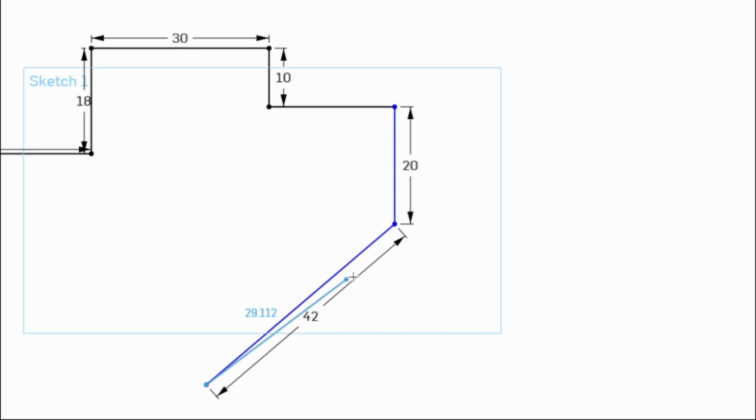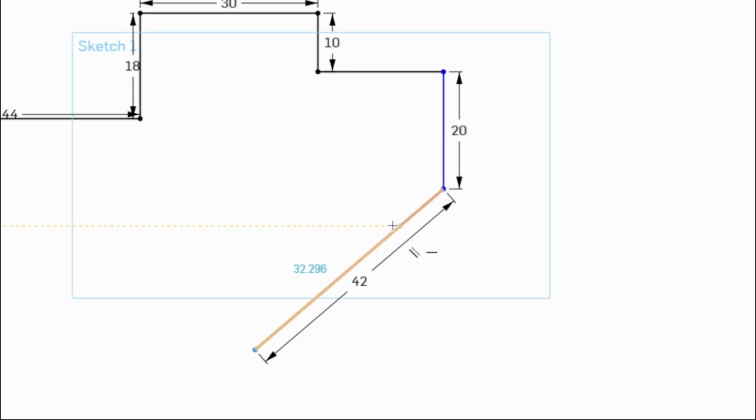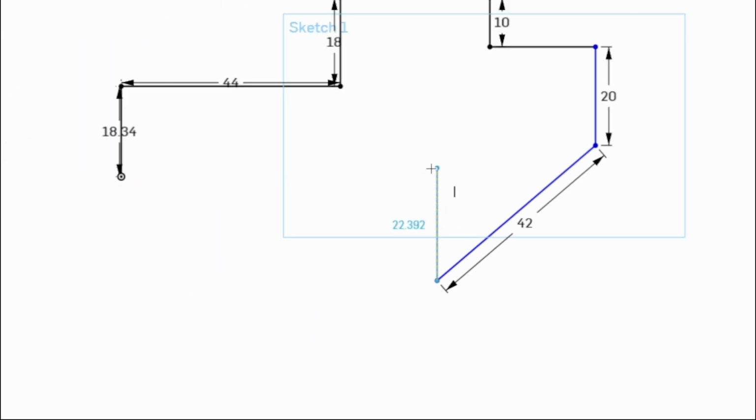It's important that when you're doing angle measurements too, if I were to draw that as a straight line or a horizontal line, I'm going to have to delete some sort of constraint. So it doesn't have to be the exact angle you want. We're going to add that later with the dimension tool, but make sure it's at least at some sort of angle that's not straight up and down or straight left and right.